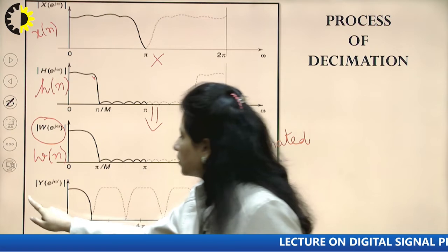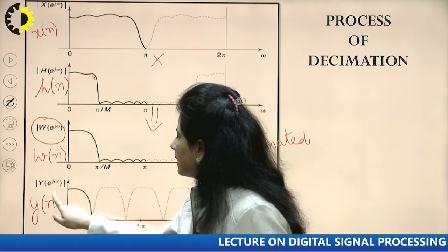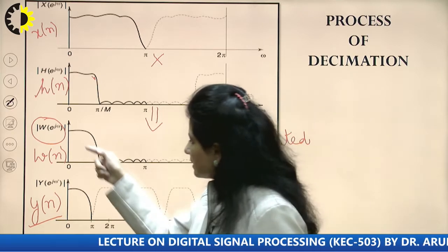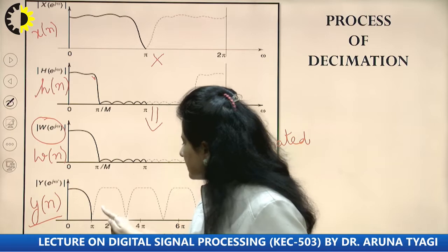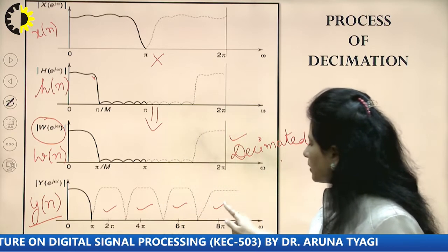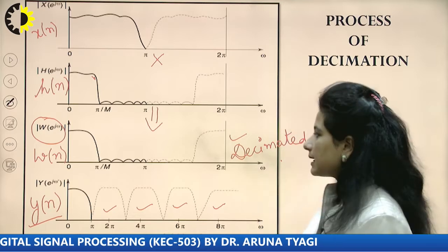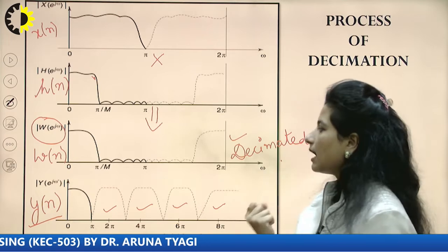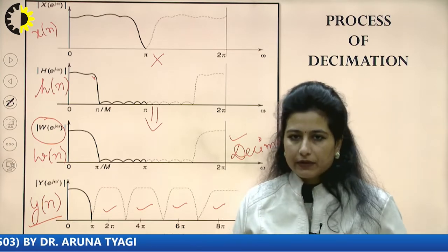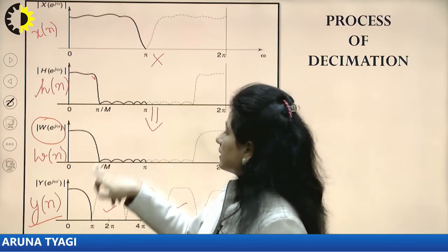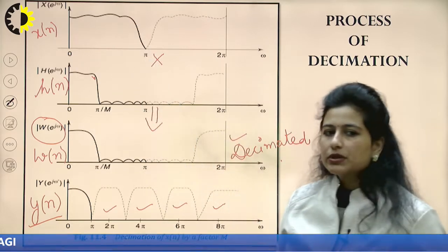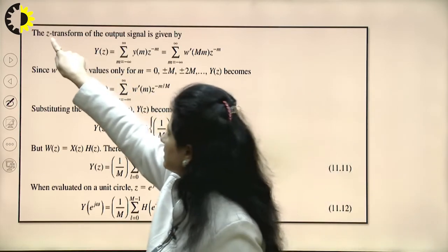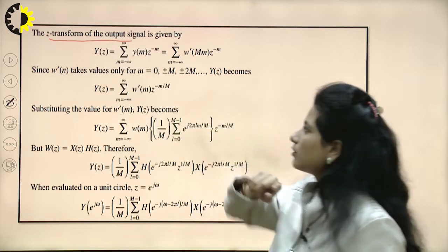So this is the output corresponding to my system, for which we have just shown the block diagram. I can see that these two are the same. What I see are the replicas of this particular signal that I am obtaining. Out of all the values of the sampled signal, I would have a few sample values, but the shape of the signal which I am giving as the input signal should not be distorted.